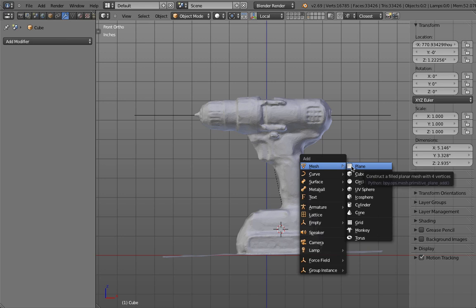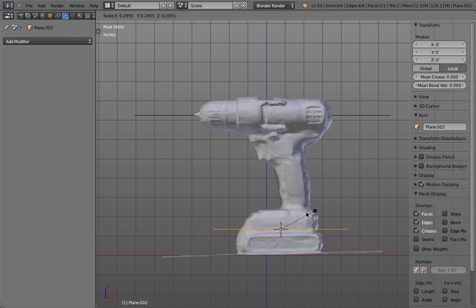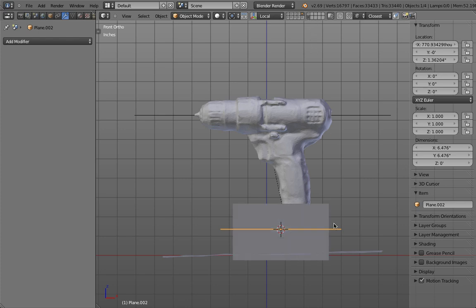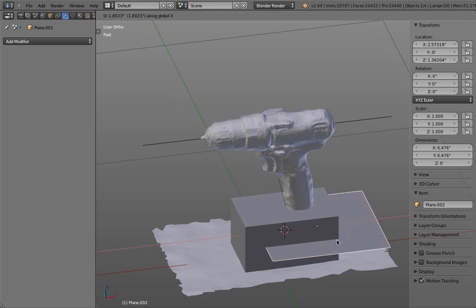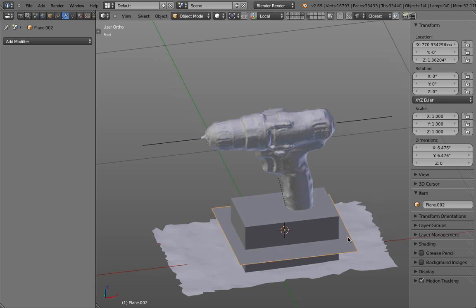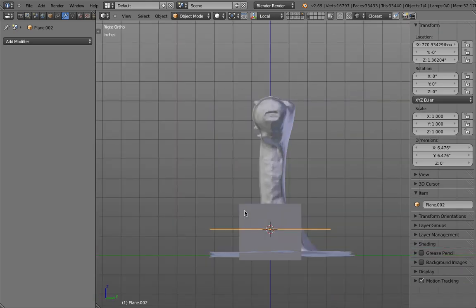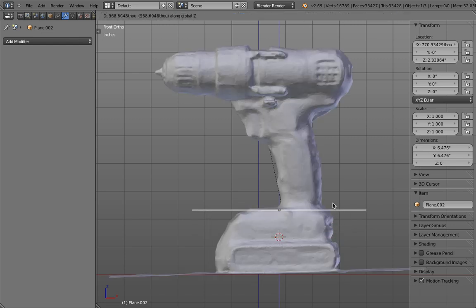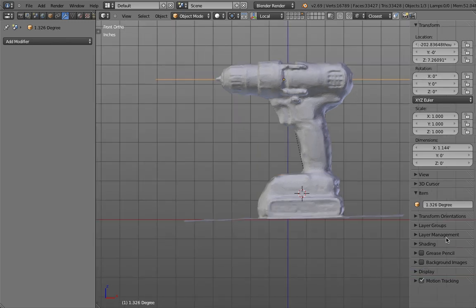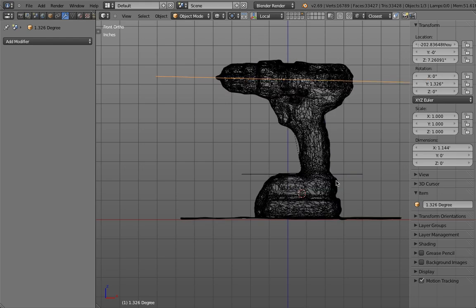So I create a plane, can scale it down a little bit, and I have to make the plane sufficiently bigger than the foam block. So this is really important. They should not stop inside. They should really cut through it. Again, think about them as knives. So I maybe bring this one over to here. And hold on. This piece actually has to be rotated. So I would like this along the y-axis, rotated. Perfect. Okay.